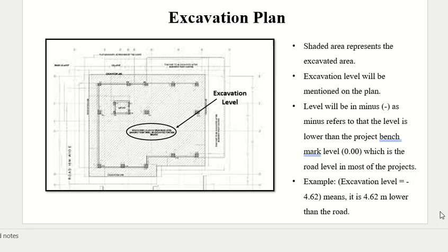In many cases, sea level is our benchmark, but in small construction projects, it can be something else. It can be the road level. Anything which is known and fixed, and will not be disturbed by your project. You can even create your own benchmark, that this is my level, and I will measure everything from here. This can be done.